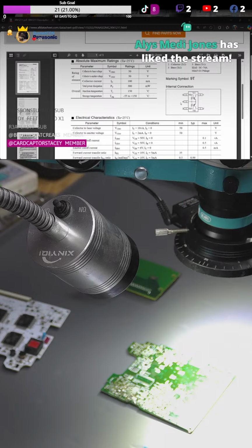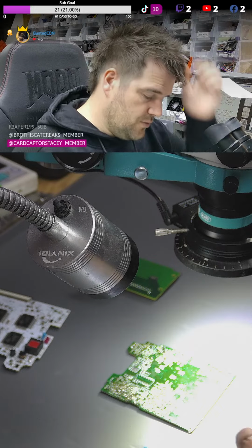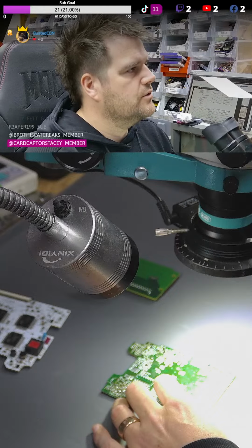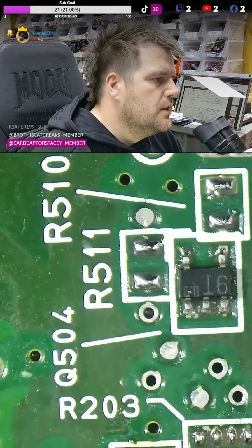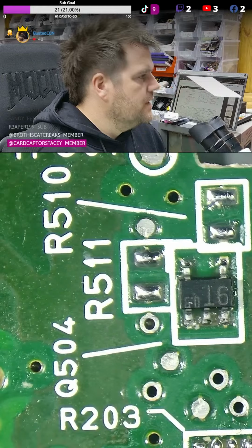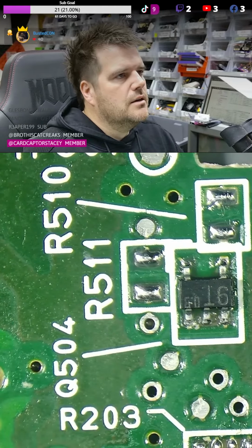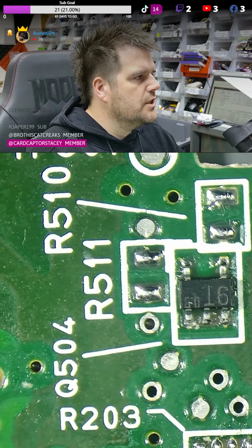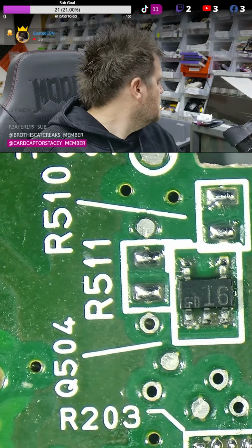So typically I'd say they'd use these for low voltage drop bi-directional switches. I'd use this setup in a 2 MOSFET configuration for a 0 voltage drop setup. So without getting too technical, I'm 99% sure that's what this transistor is. So Q504, that's what I'm going to go with, and just write it in the bill of materials, which is over here.